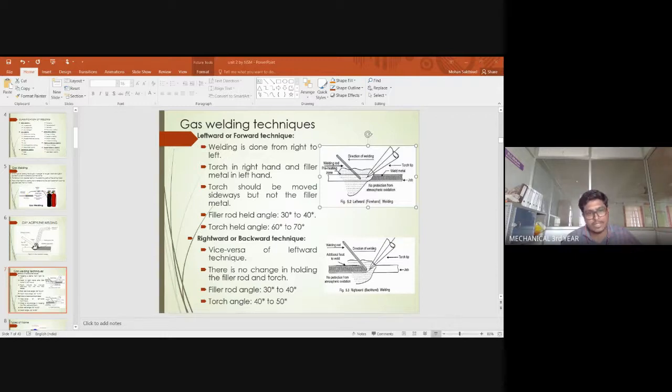And here you can see a TIG filler rod. This rod gets melted and gets deposited over the workpiece, that you can see over here. So let us see the arrangement again. Here you can see, in order to supply the inert gas, you have a small projection on the welding gun. We'll call it a welding gun, which carries the electrode connected to the positive or the negative terminal, and the workpiece is connected to the other terminal of the welding power source.